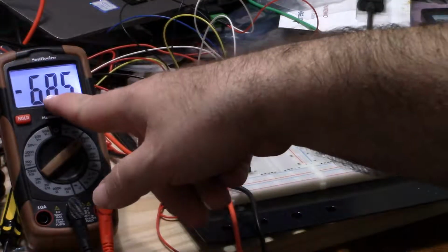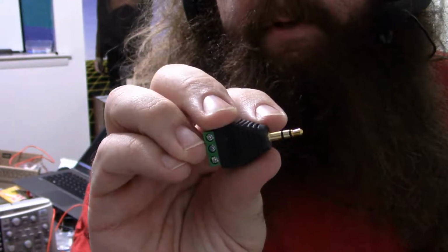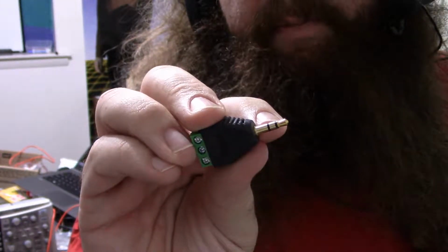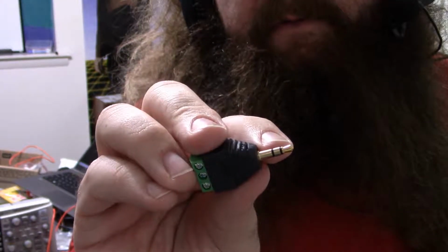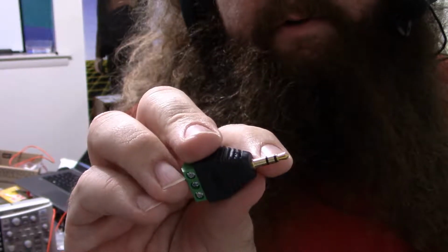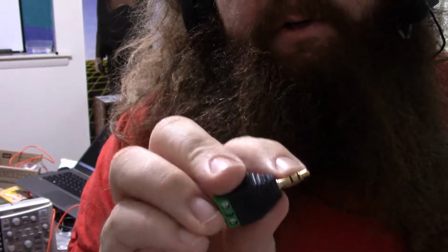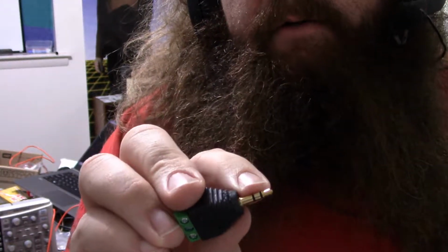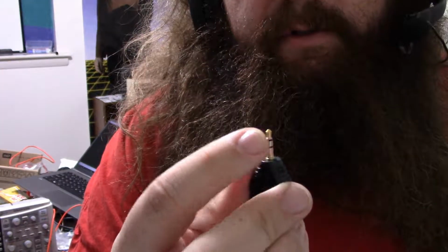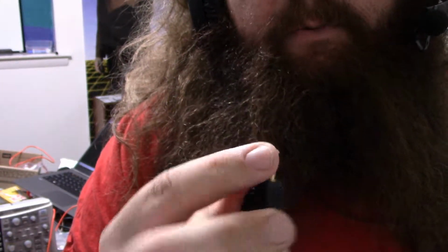There you go. So this answers another question as well. So if you recall, we have our TRS, tip ring sleeve. This is what's plugged in. But remember a mono microphone? It might just be TS, tip and sleeve. Only one conductor plus ground. But it's the same plug, the same size, and they're compatible. You can plug a mono into a stereo and a stereo into a mono. If you plug headphones, stereo headphones into a mono output, you'll just hear something in one ear and not the other.